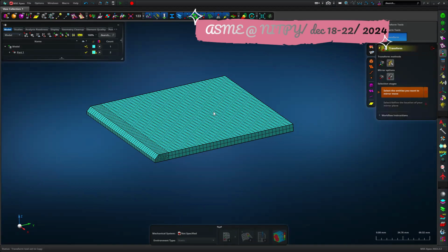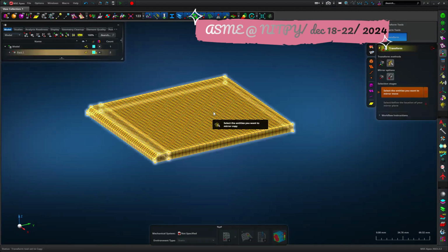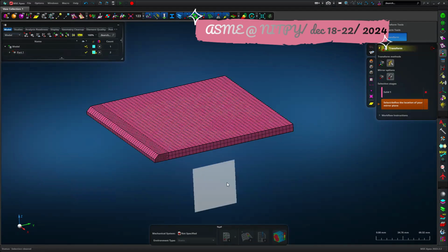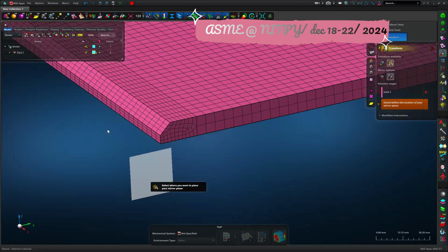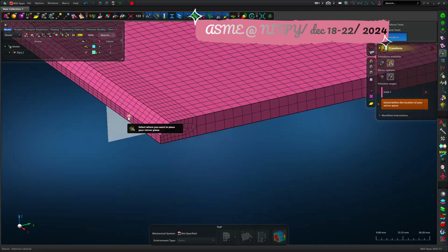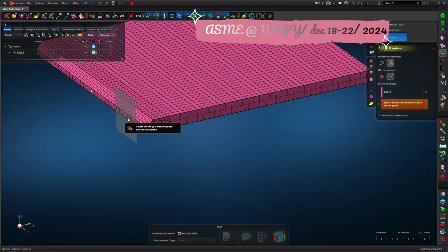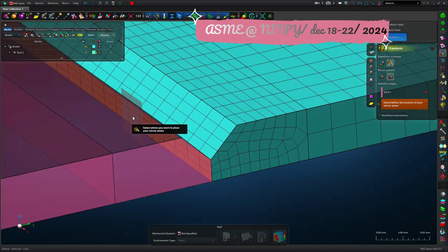Next step is click on the geometry. And you will get a plane kind of thing on the screen. You select the plane here, where this face, you can see it getting mirrored. If you select the correct plane, it will get mirrored in the right location. That vertical plane. Yeah. Zoom in a little bit and execute that.